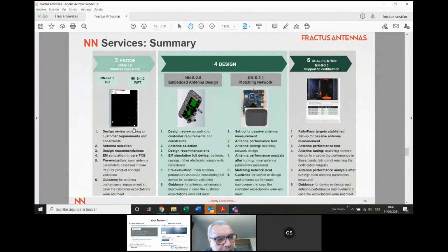We are also preparing application notes where we show the customers the performance as a function of the distance between the antenna and the metal element. It cannot be located on the metal element. The antenna cannot be touching the metal. But if you take some precautions, and we can discuss it in the initial interactions with our engineers, to put it a minimum of 5 millimeters away, then this is working.